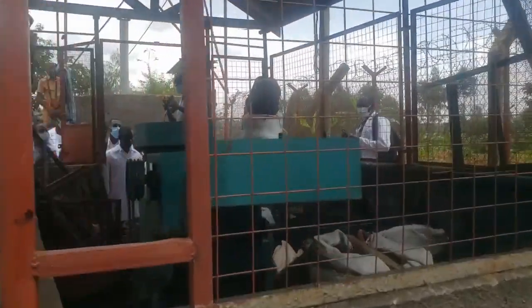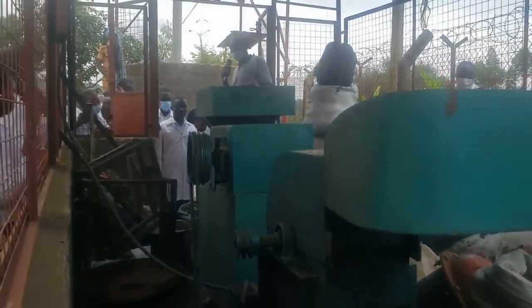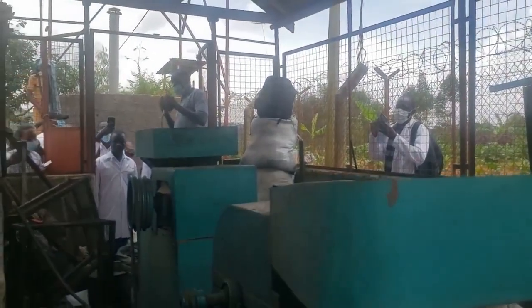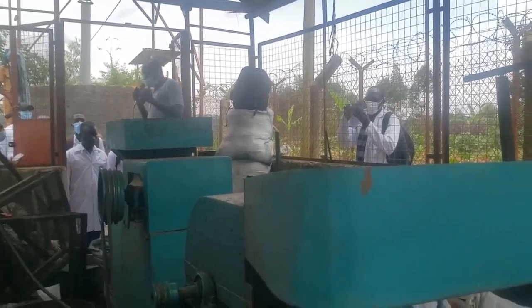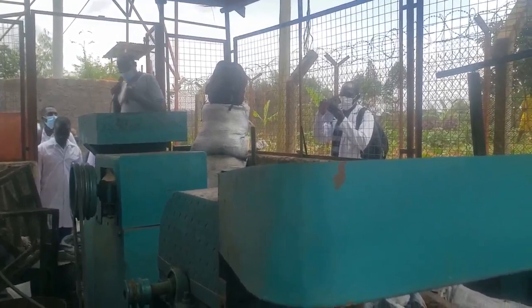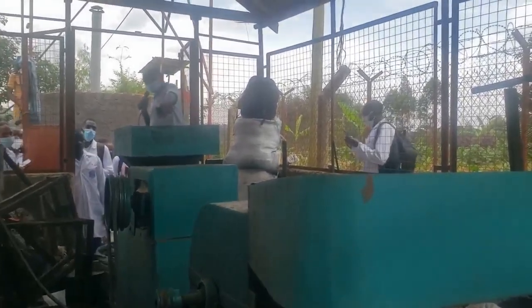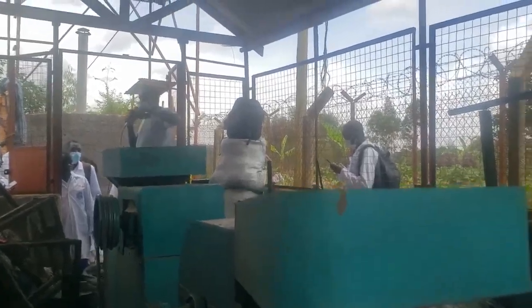After drying, you separate it in two. You can mix in a binder, maybe crushed coffee husks or rice husks, any other binder that you would want. Then you carbonize it, and you can compress it using the machine or manually.